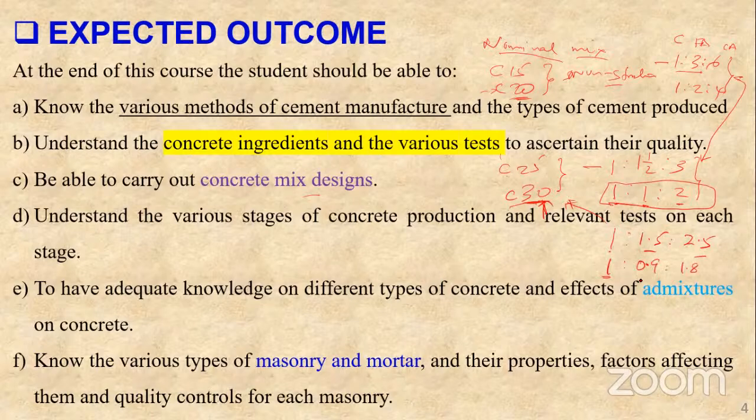Okay. I believe, now that you know the mathematics of ratios, this should not be something to worry you. You should be able to see that when I reduce this, the cement content is higher as opposed to here. Now, another thing that you need to note is that when you say cement class C15, we are saying that the strength at 28 days is 15. So class 15 is 15 MPa. What is MPa? Newtons per millimeter squared.